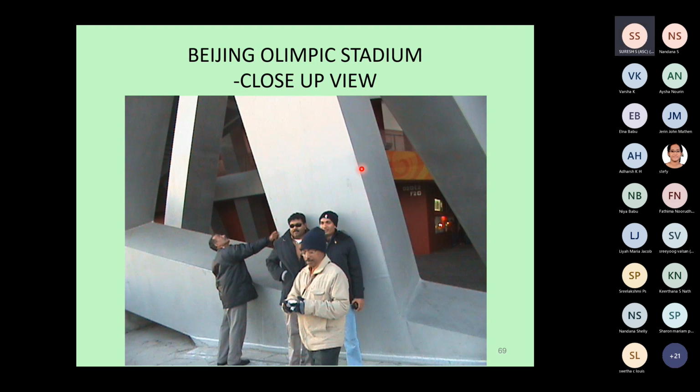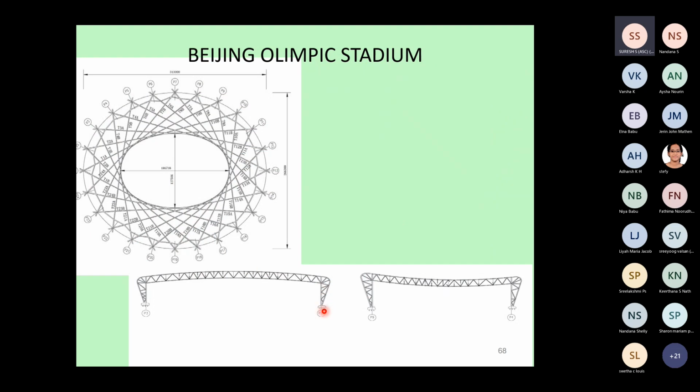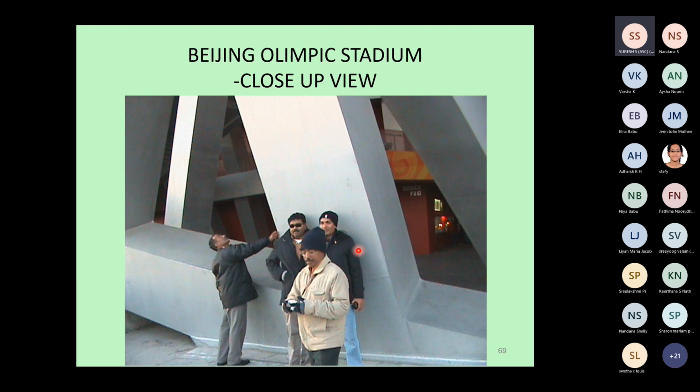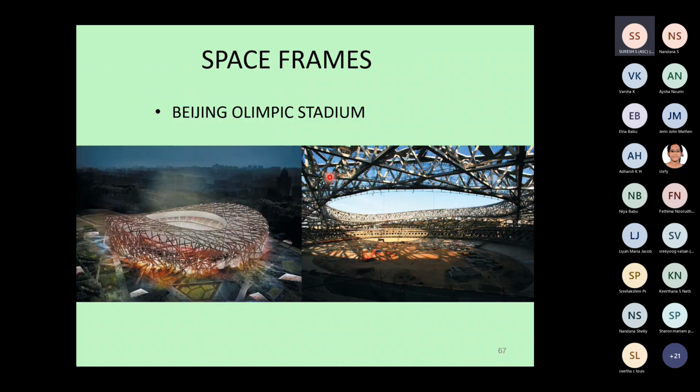You can see a photo in which that leg element, with sizes of some of the people standing there, huge sizes like that. So you were seeing this part of the leg, which is a plated box. This is a 4-plate box. Inside is hollow. So such huge steel shell elements are the leg of that portal, which has to span across 200, 300 meters across the stadium to give you a nice view from inside the stadium.